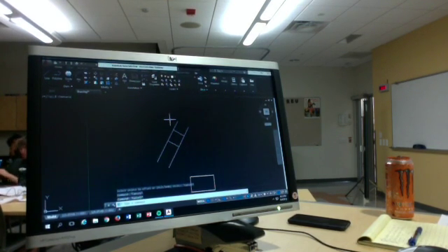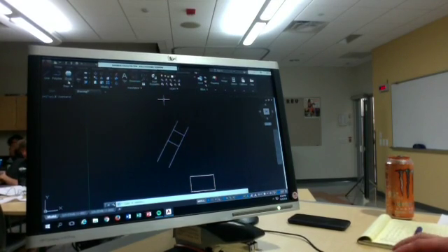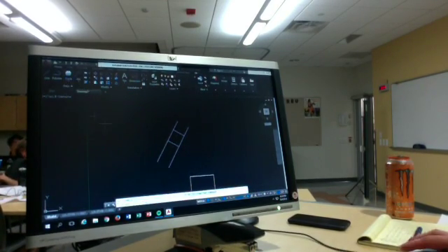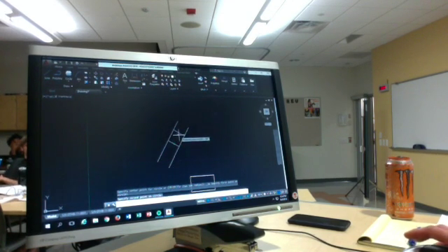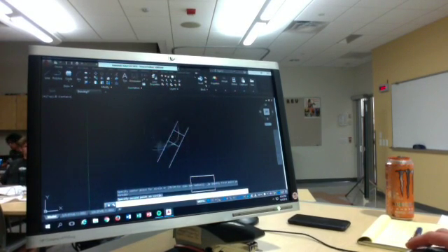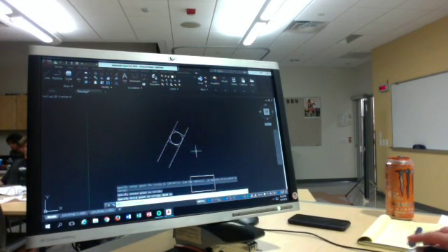Now I drew a circle that's perpendicular to the other one and then offset it. So this is a perfect box. But you need a circle in there. So you can actually make a 3-point circle. So 1, 2, and if you're in a command and you want to use a near snap, you just type in near. And then it'll go anywhere near where you want it to. Click on there, you have a 3-point circle.